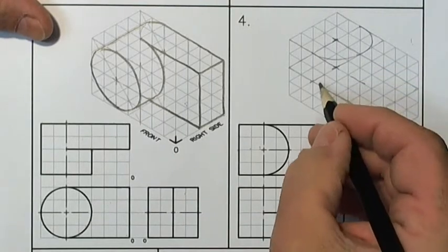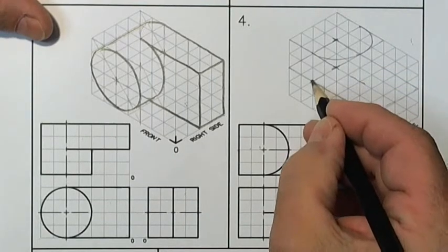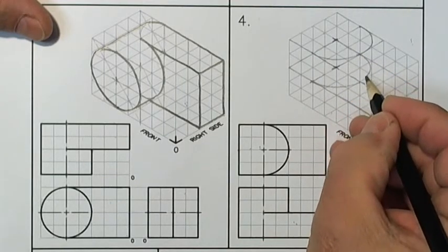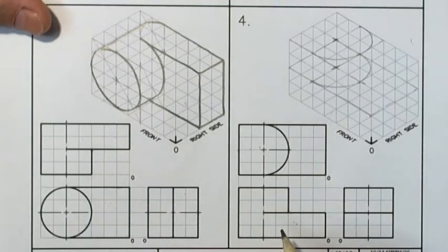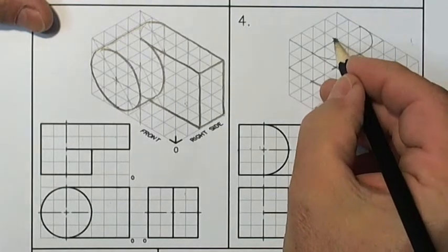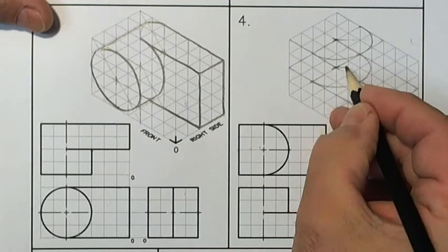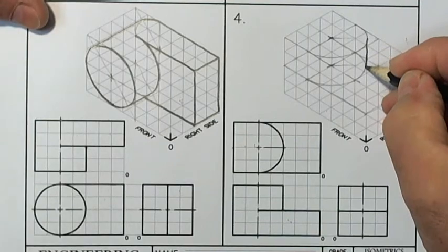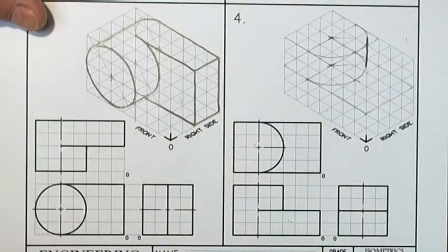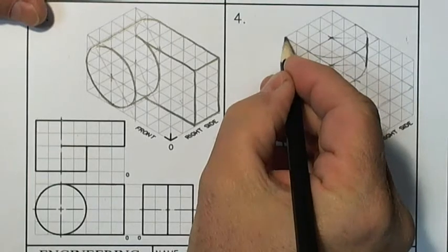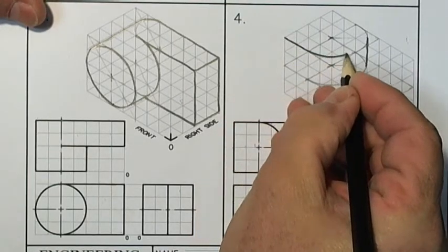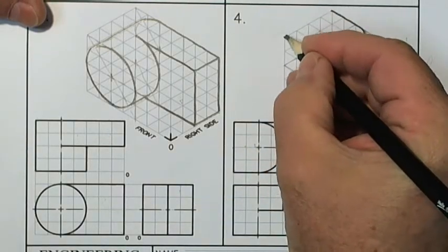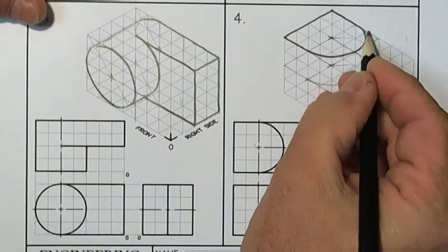and there's my parallelogram. Here is my flat arc. Here is my rounded arc. When I put in the long diagonals, once again, I'm directed as to where the edge occurs. And with that done, I'll simply go over, add my visible lines,